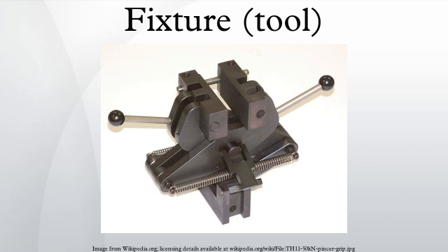Because drills tend to apply force in only one direction, support components for drilling fixtures may be simpler. If the drill is aligned pointing down, the same support components may compensate for the forces of both the drill and gravity at once. However, though monodirectional, the force applied by drills tends to be concentrated on a very small area. Drilling fixtures must be designed carefully to prevent the workpiece from bending under the force of the drill.